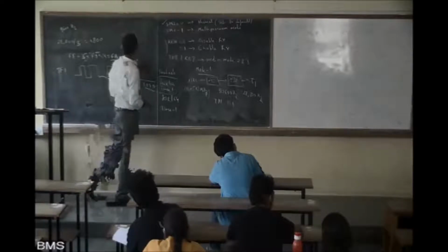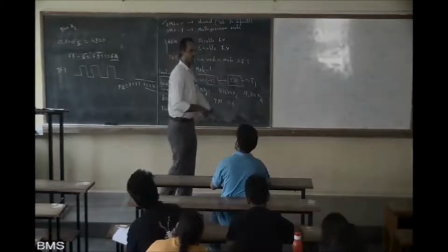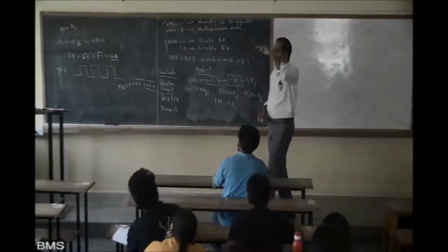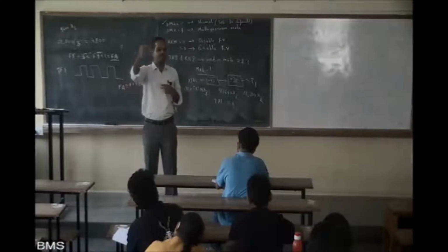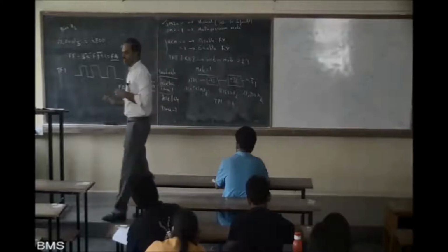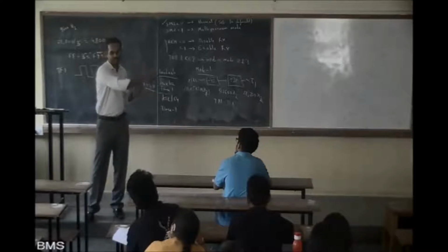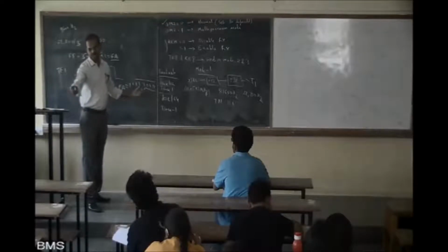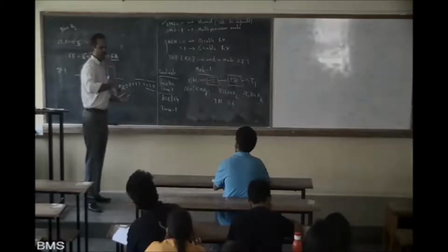Done. You are clear with what is inside the UART stuff. Inside UART, there is SCON and 2 registers. Both are in the SFR register. SCON controls in what mode the serial communication should happen. What is the TI flag? When is the data transmitted? When is the data received? Whether the receiver is enabled is set in SCON. Sending data is through SBUF. Receiving data is through SBUF. That is 8-bit mode, with 1 start bit and 1 stop bit, and for that the baud rate is decided by timer 1.